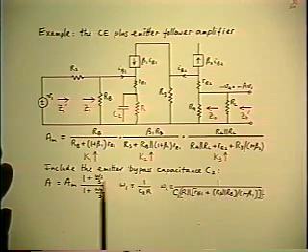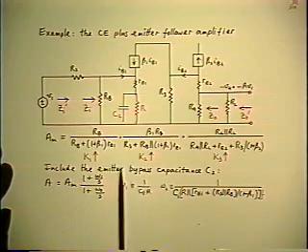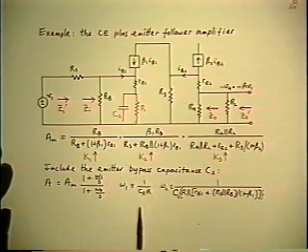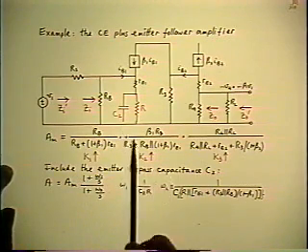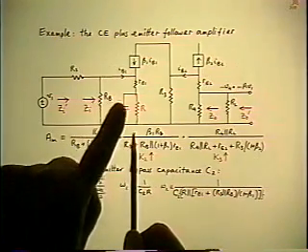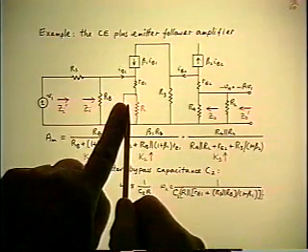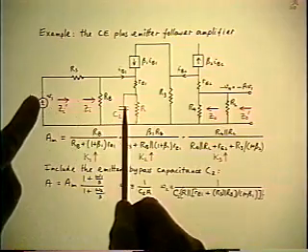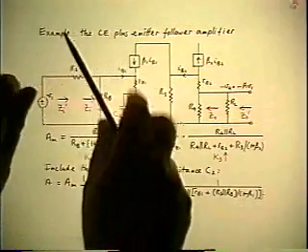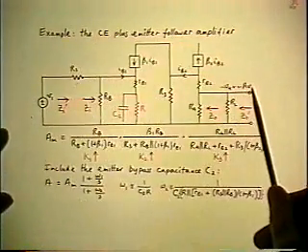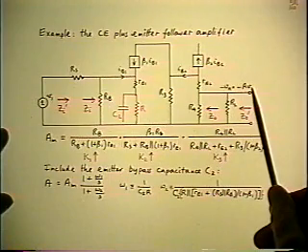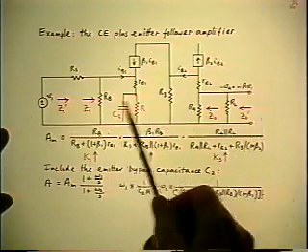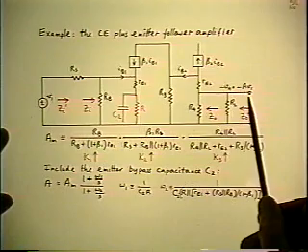The other half is the zero, which is going to be determined by the same capacitor and the Rn. To find the Rn, replace the capacitor with the independent second source, restore the original input, imagine that you twiddle the two of them to null the output, propagate the null back to the second source and see what happens to its current.